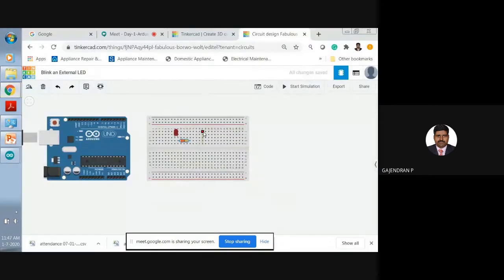Yes. You have to pick the wire. Don't search anywhere. Just click where we need to start the wiring. Just click the terminal and move it. Immediately the wire option will appear. By default, it's a green wire. I will show you how to change the color also. I need to route the wire in a very clear manner. Don't immediately go and connect it to the required terminal. You want to drag the wire in a neat way. Once you left click the mouse, it will get a bend.